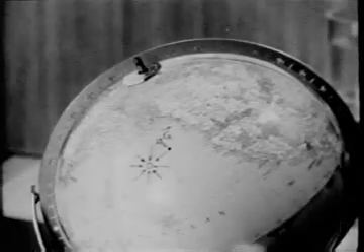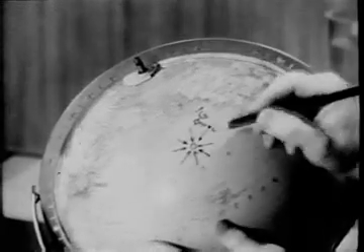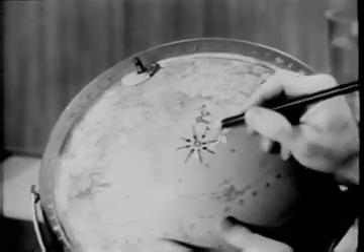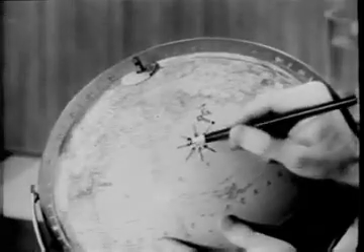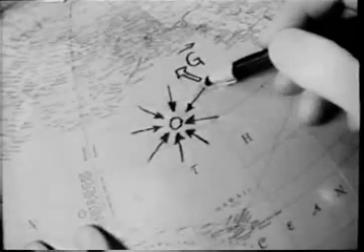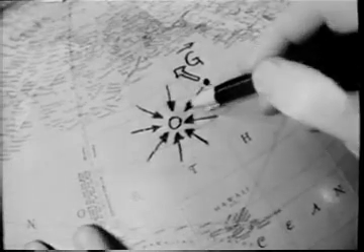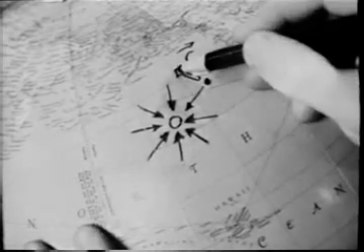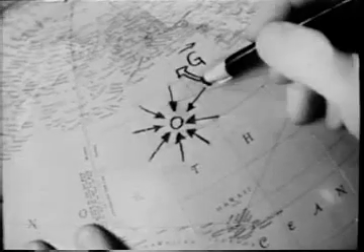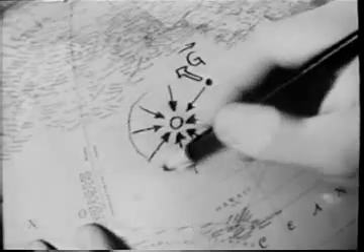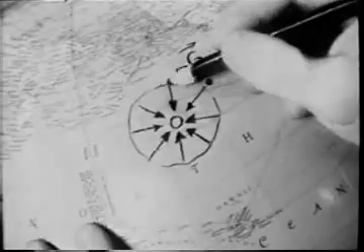Let's imagine that this is the drain. The water flows readily inward from all directions. The Coriolis force acting on a fluid particle in the northern hemisphere, as it moves radially inward, is circumferential and counterclockwise. This force, integrated around a circle, contributes a counterclockwise torque in Kelvin's theorem.